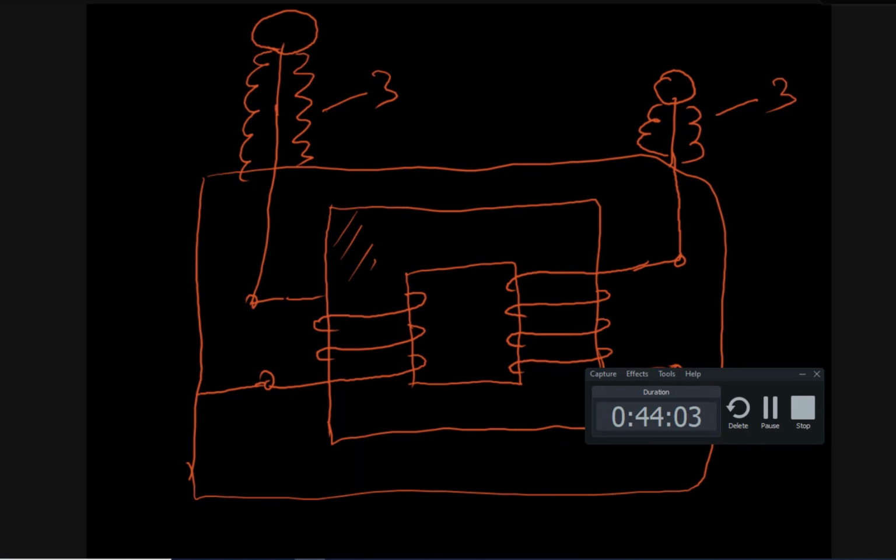You see, the winding has a resistance, and then there is inductance associated with this winding, because it is a winding. As long as there are turns, of course, even a single wire will have inductance, because there will be magnetic flux associated with even a single wire. So if there are turns like this, there is inductance associated with them, and there will also be capacitance between these turns, because the turns are separated by a certain gap.